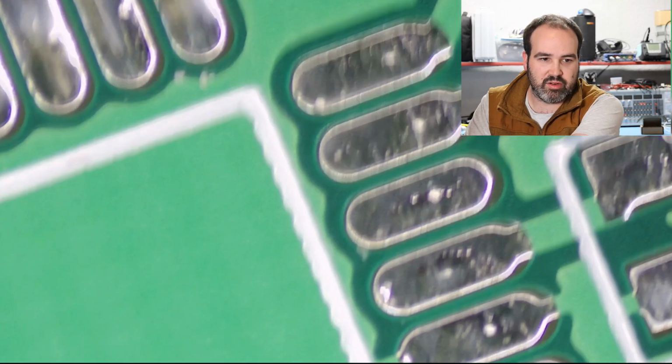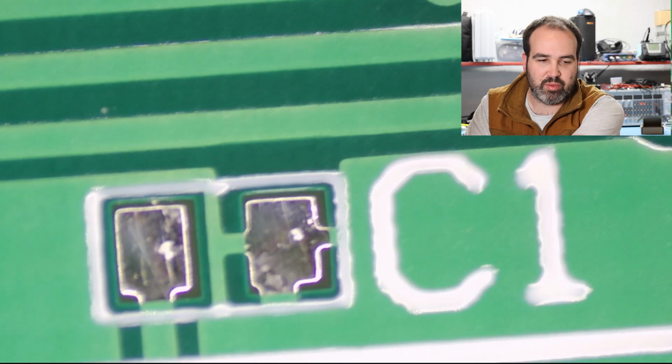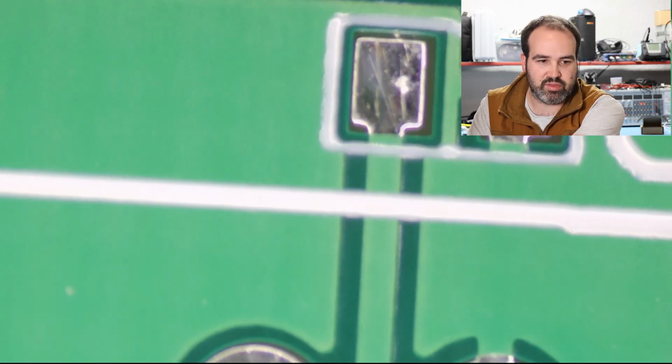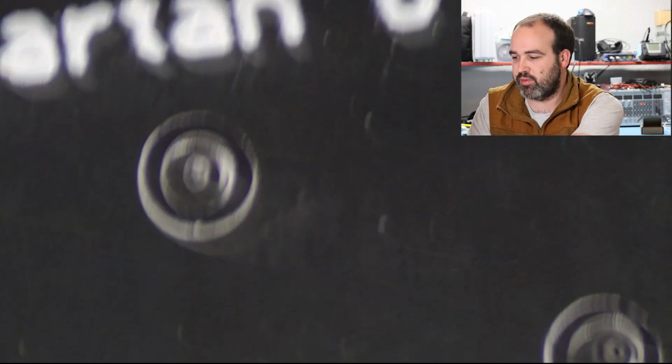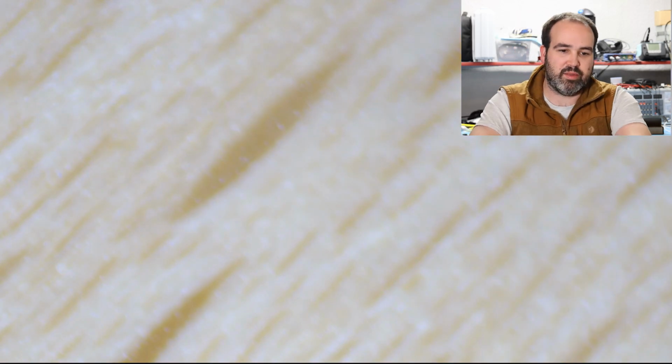Sometimes it is a silkscreen process, where there's an actual template, whatever you would call that, that you push over with the classic silkscreen process. So the quality can vary. This is all stuff when we go to order. There are different options you often have. But okay, there's your solder mask.